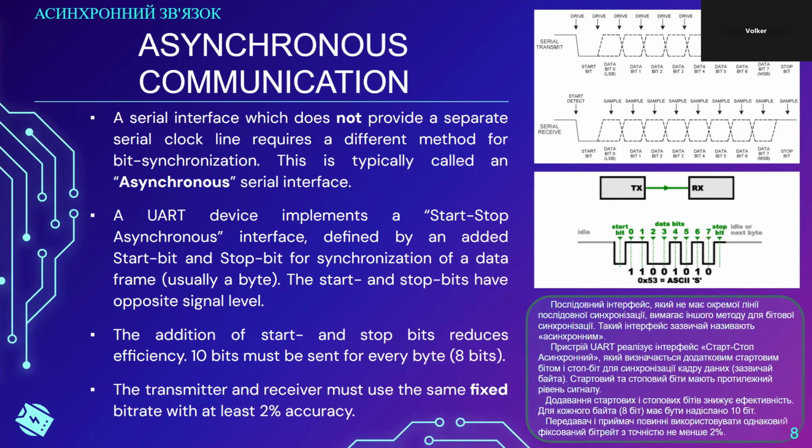So if we have 10 bits, and it can't be more than half a bit time, we have 20 half bit times. 1 divided by 20 is 0.05, so that's 5%. Now we have a transmitter and receiver, both can be off in the opposite direction. So they have to be accurate to 2.5%. Now we are taking 0.5% off as margin, and that's how I'm getting to the 2%. That is generally the rule of thumb. That's where the 2% number comes from.